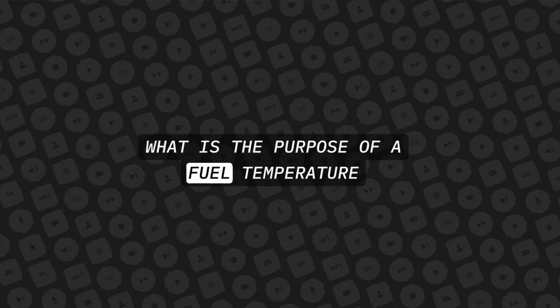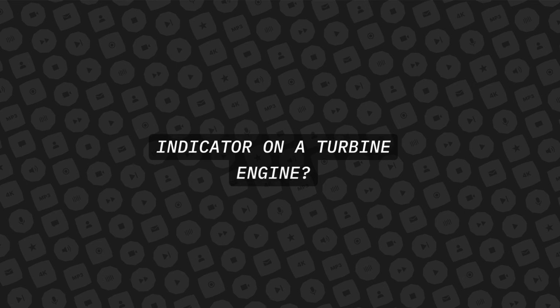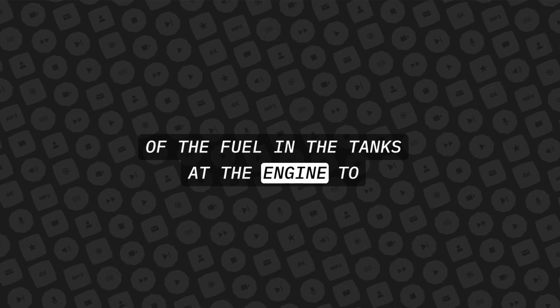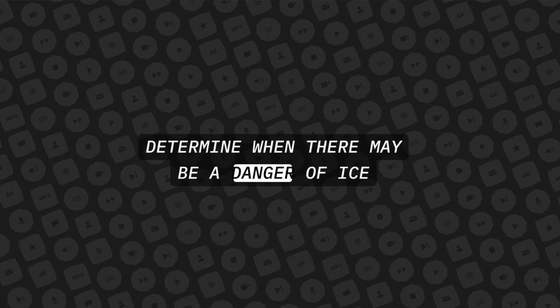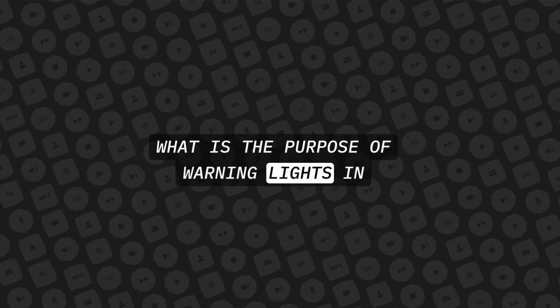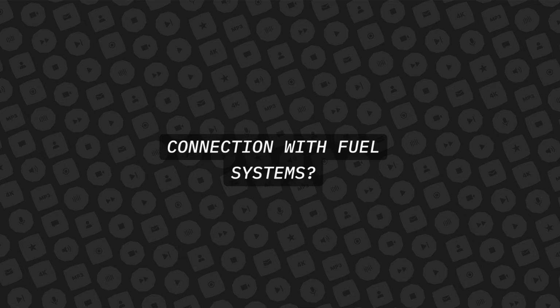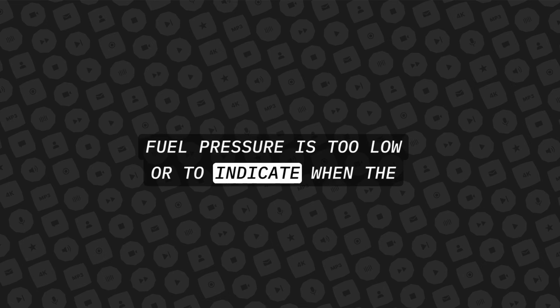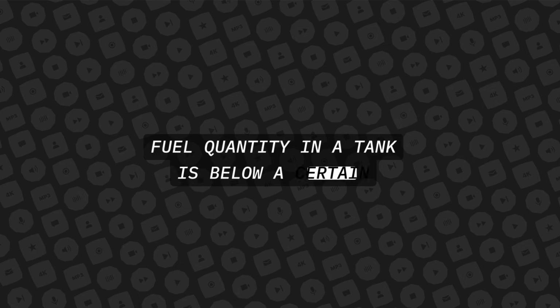What is the purpose of a fuel temperature indicator on a turbine engine? It is a means for checking the temperature of the fuel in the tanks at the engine to determine when there may be a danger of ice crystals forming in the fuel. What is the purpose of warning lights in connection with fuel systems? Warning lights may be used to indicate when the fuel pressure is too low, or to indicate when the fuel quantity in a tank is below a certain amount.